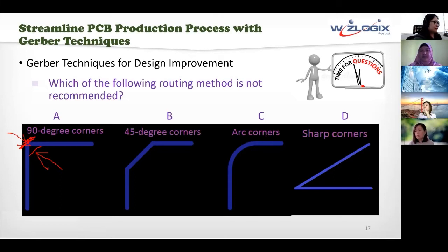Okay. So just imagine if you have any other trace running here, this under etching will actually allow this end of the copper to touch another trace, if you have any trace here or any other series of traces here or buses. So that's a potential manufacturing problem.